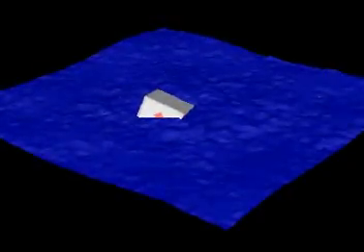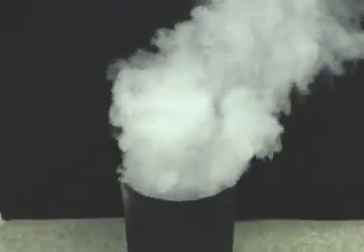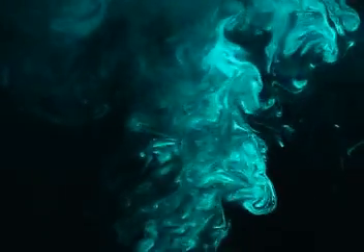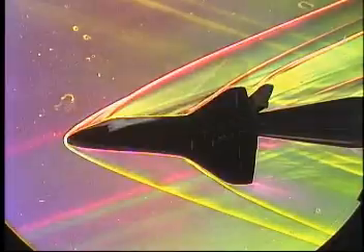In order to produce a fully three-dimensional flow, we fed theatrical fog into the bottom of this can. It makes a messy, turbulent 3D plume. A modern way to study such a complicated flow is to illuminate it by a thin sheet of laser light, thus slicing the 3D flow into two-dimensional sections. Many flows of practical interest are very three-dimensional.